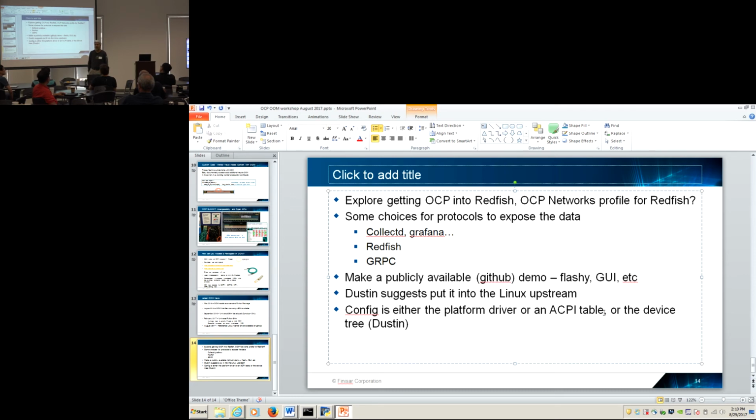They're not nearly as carefully placed, and the driver writer would need to decide whether they are where you want. As a driver writer, I have put some more in, took some out, and moved them around. But the error codes, the actual proper handling of real errors, like when you called I2C and it gave you back an error code, all came from production code from Cumulus. I didn't take it out on purpose, but I wasn't careful about making sure every change I made propagated correctly. So my driver is not yet hardened and production ready, but it's based on a hardened, production ready driver.